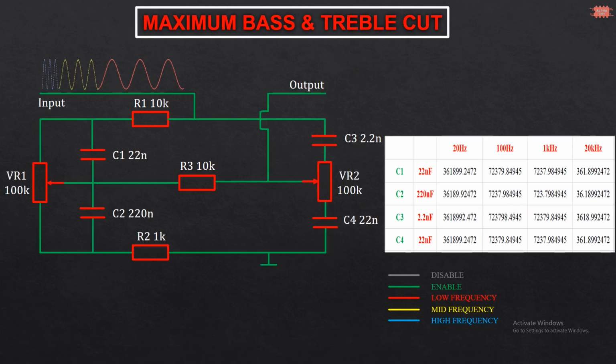I suppose that the wipers are set to minimum, so that, C2 is inactive because of short circuit. VR1 and VR2 are inactive because of high resistance. The capacitor C3 is also inactive because VR3 is inactive. The circuit is redrawn as follows.